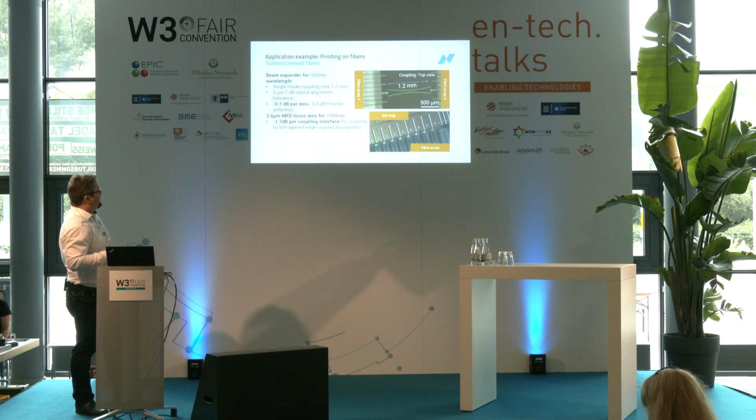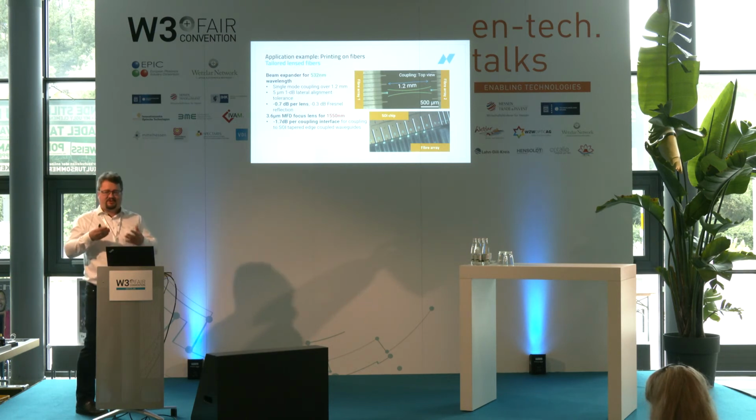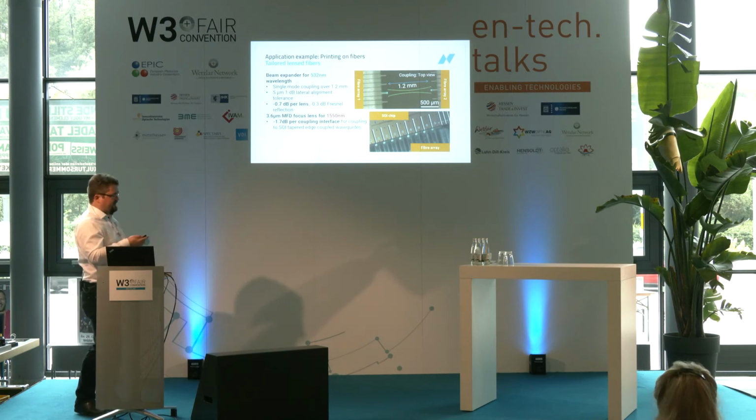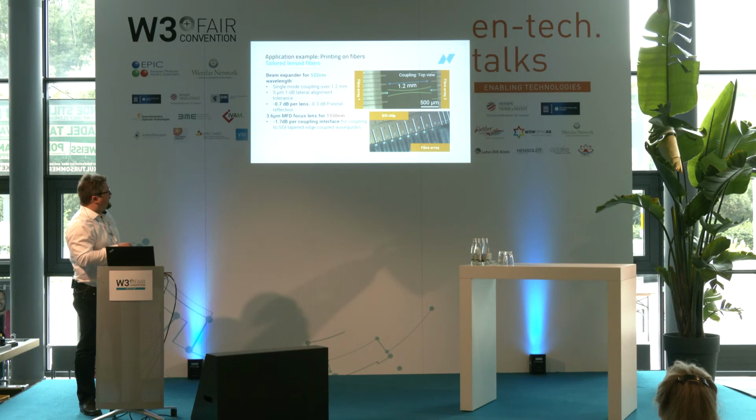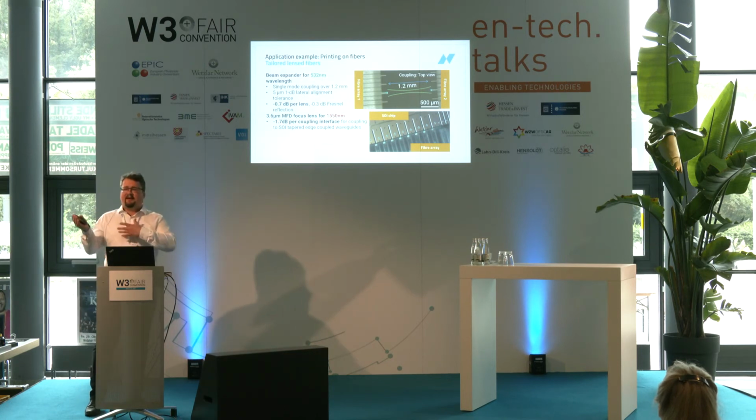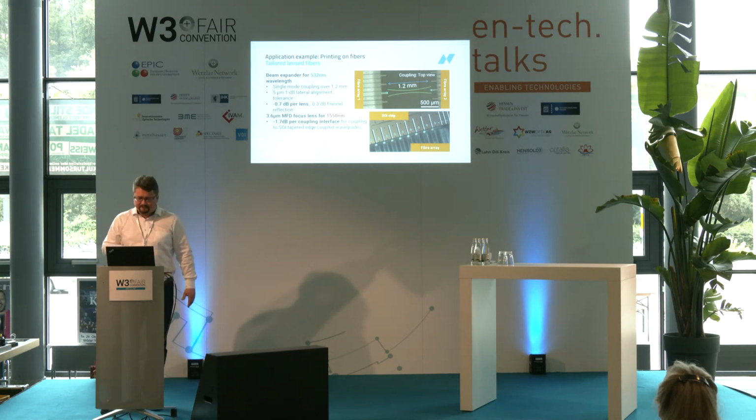And up here, we find that we have a very moderate loss of just 0.7 dB per lens, so 1.4 dB total, of which 0.3 dB per lens is actually just reflection losses, which could be combated very easily by coating the lenses anti-reflectively. And then down here, we have been looking at the situation lens and waveguide. And here we have a total loss of 1.7 dB per interface. We were looking at different wavelengths here, but in principle, anything in between would also work.